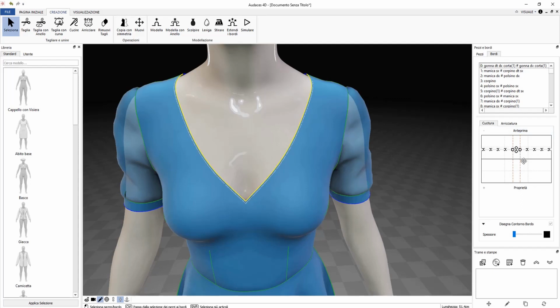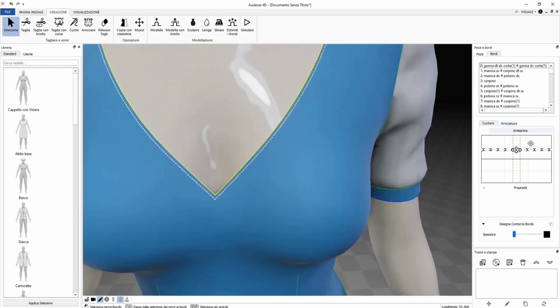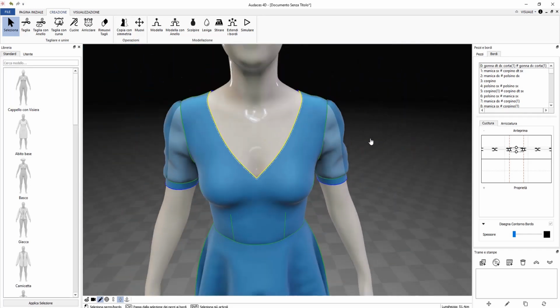Here we can change the properties of the seam. The right rectangle will show a preview of the seam. By holding down the design of the seam and dragging it, you can move it in position. Notice on the garment that it will do the same actions. And by dragging the dots, you can enlarge or reshape it. We continue with the other seams, repeating the same procedures.